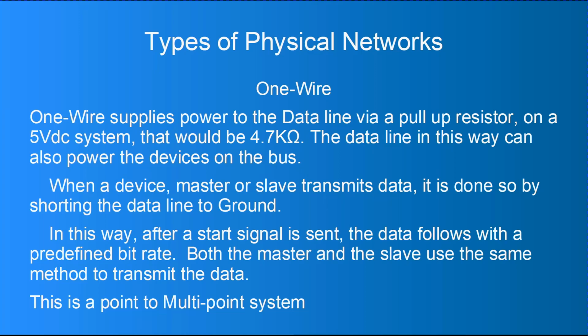At the end of that time, it will go back to having it as an input, and it will send the command to an individual sensor, report your result, and then the individual device will return that data. It's a master-slave system. The slaves are not permitted to return data or control the bus in any way until they are told to do so. And only one slave is permitted to operate the bus at a time, or the master for that matter.